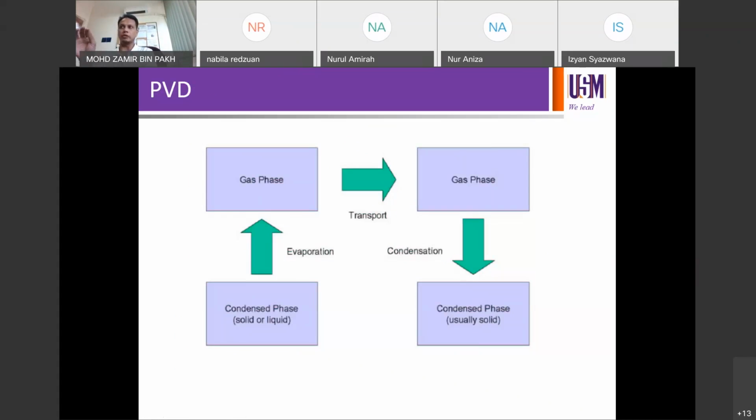And then the moment you have enough vacuum level, you turn on the current, initiate the resistive heating process, then you will evaporate the solid material into gas phase, and then the gas needs to travel through a distance to get from the source to the substrate in order to be deposited. So the distance that they have to travel has to exceed the separation distance between the source and the substrate.